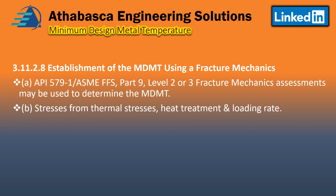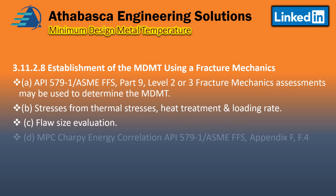This kind of criteria. And you can look at flaw size evaluation as well. And there's a Charpy energy correlation that can be found to assist with the evaluation, and it's found in Appendix F or F4. And I believe it's the pre-2012 edition that can assist you with determining the required Charpy energy factors.